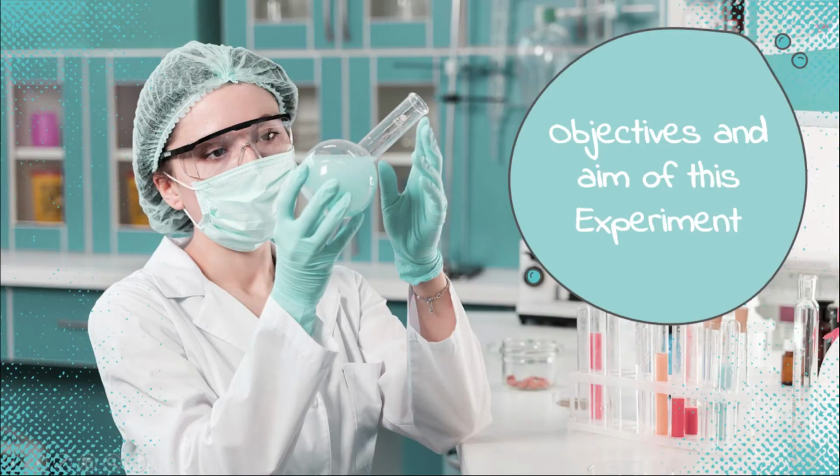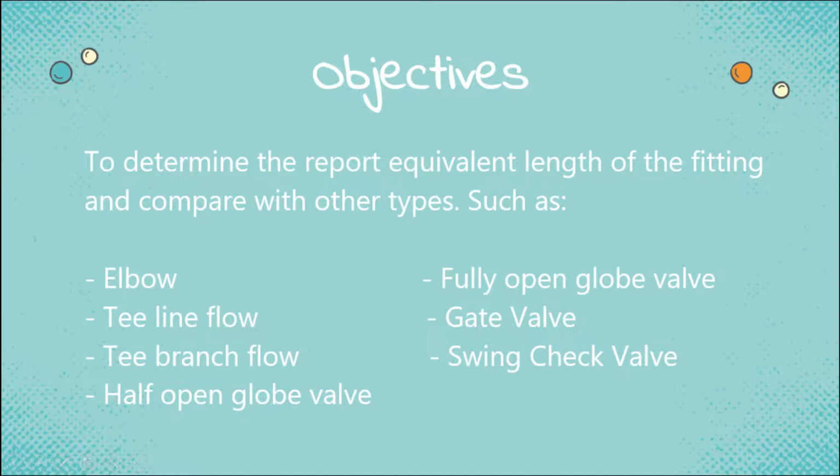The objective and aim of this experiment is to determine the equivalent length of the fittings and compare them with each other by type, such as elbow, T-line flow, T-branch flow, half-open globe valve, fully open globe valve, gate valve, and swing check valve.